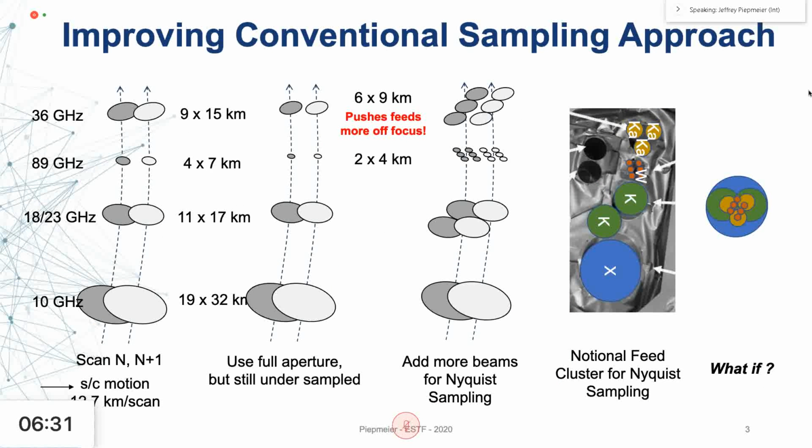Okay, so I'm going to describe how the proposed solution was arrived at and how it works here. And I'm going to pick on the GPM microwave imager again. The engineers at Ball Aerospace did a fantastic job optimizing the antenna design, having to operate from 10 to 200 gigahertz. But because of this, they had to give up Nyquist sampling at the higher frequencies.